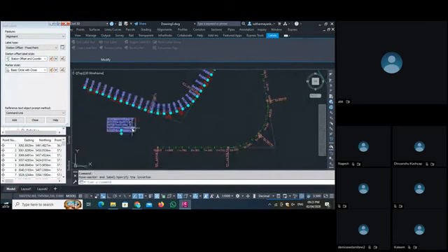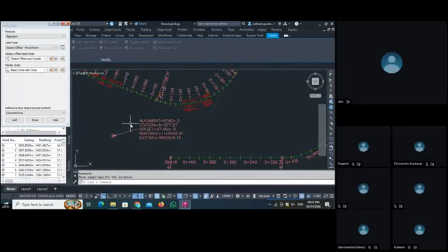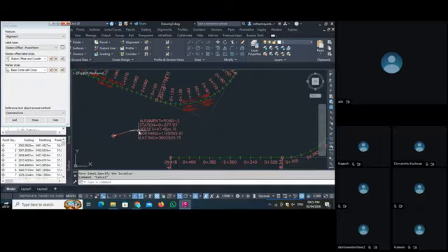You can put it here also. You use these square marks and put it anywhere. See, if you mark some point, like if you want the description of some point on the location, you have to add this point here on your alignment. And you can export that point with the alignment. So whenever the surveyor gets your alignment, they understand where on the live location they have to mark. So we provide this type of point to them with the help of the station offset.